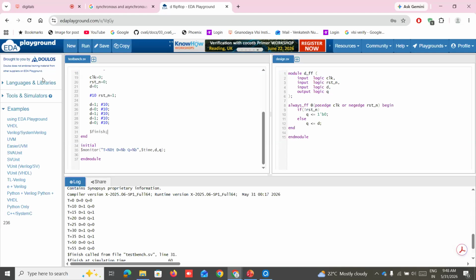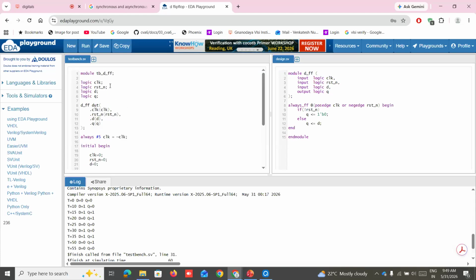One data flow model I have explained. Then based on the data flow model, you will write some design codes and then write the test bench. I have explained how to write the test bench and what things are there. This is the test bench explanation. This is the ports declaration. After that, DUT instantiation. For this DUT instantiation, I have explained two types: name based instantiation and position based instantiation. Tell me, this one is which type of instantiation?